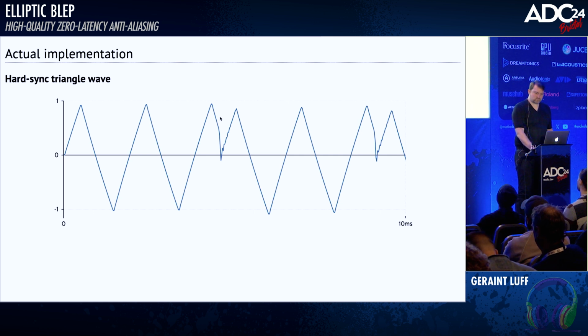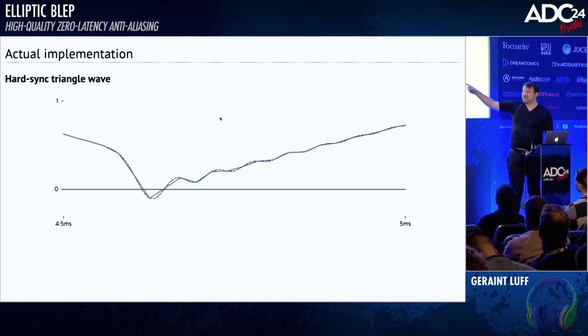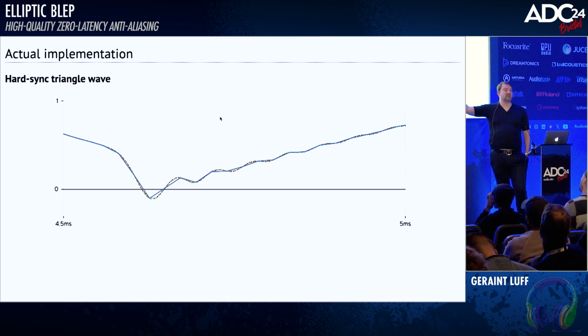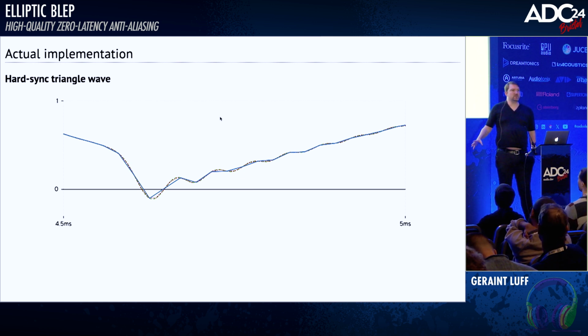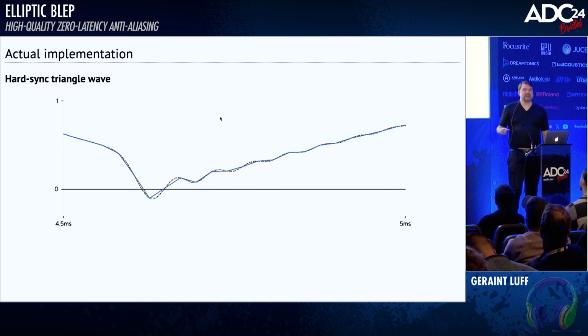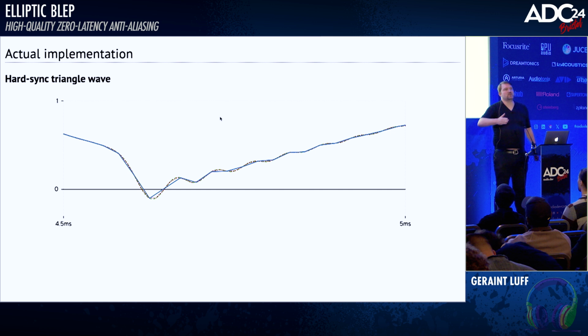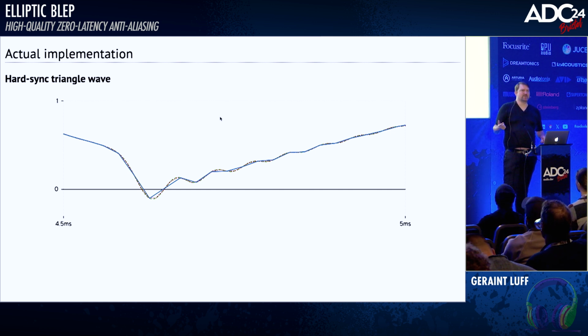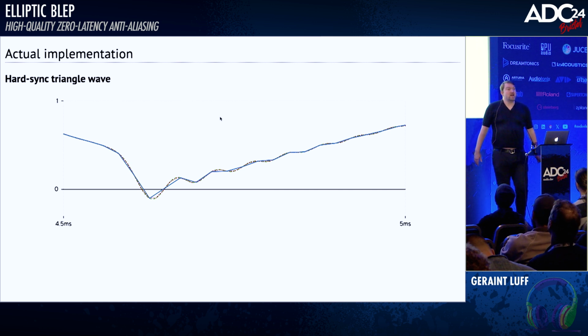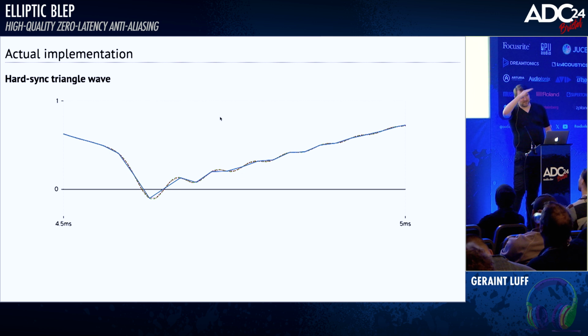That's our Gibbs phenomena. We're going to zoom in on just this little section here between 4.5 and 5 milliseconds. I've rendered this same waveform; this blue one is at 44.1 kilohertz. And I've run this exact same code at 96K and at 384K, which is 8x oversampling at 48K. And you can see they line up, right? What's happening is, because I've used a static filter where the cutoff is always 20 kilohertz, because of the way that I baked in the high pass, if you scale it, then the high pass gets higher, and that could go wrong. But the point is, even at 44.1K, we are correctly sampling this very smooth, anti-aliased, low-passed